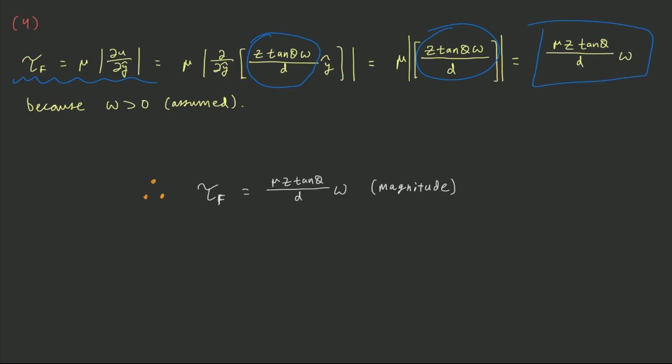And one more time, it's worth noting that the magnitude of the viscous shear stress within the oil is indeed a function of z, as shown here. And that's because it has to be. The tangential velocity of the conical viscometer is higher at the top of the viscometer than it is at the bottom. So due to the no-slip condition, the velocity profile at the top of the viscometer is of a higher magnitude on average than the velocity profile at the bottom of the viscometer.